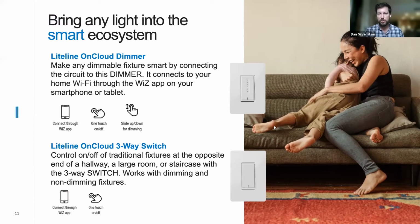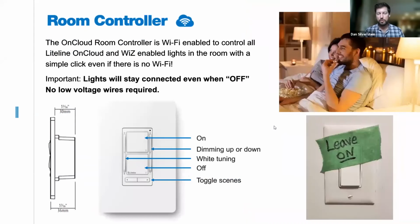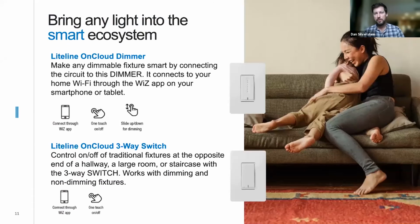Dimmer and switch are for traditional fixtures. Room controller is for smart fixtures. The dimmer and switch count as a smart fixture. So for a three-way application or four-way or five-way, doesn't matter. The load goes on the dimmer, and then the room controller controls the dimmer, and you can have as many of them as you want.